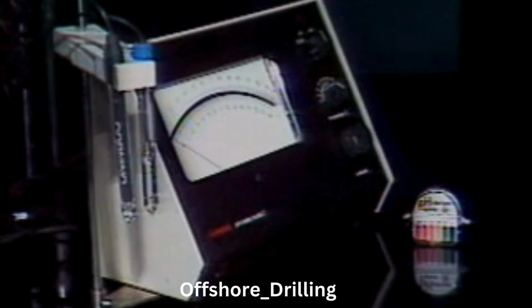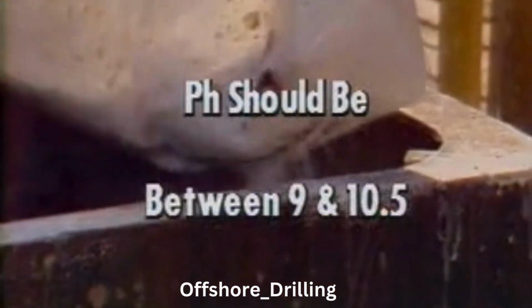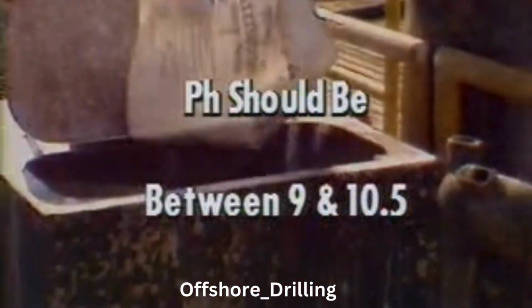pH affects the mud's ability to dissolve additives. Low pH mud also corrodes pipe and interferes with the viscosity control of bentonite. Caustics are added to the mud system to control the pH level. It should usually be about 9 to 10.5.